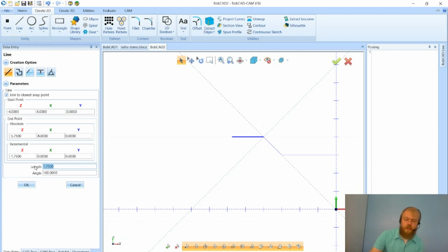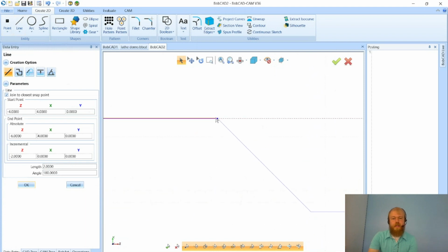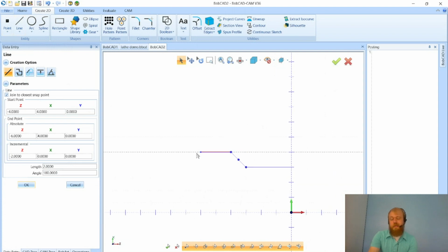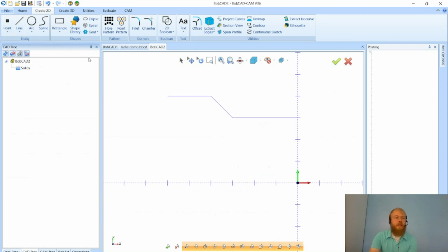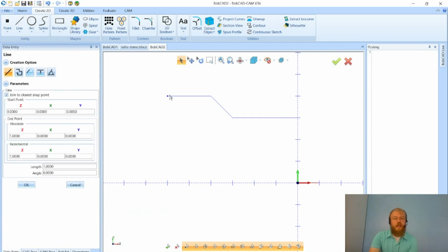Let's go over 2 inches. And maybe we'll just focus on that. We'll make these a couple of arcs here, and then I can make the solid model here by first closing things off. So if we're looking at the turned part here, I'll go to line. From the endpoint here, we'll go down to our z-axis, z0 there, and click there. And from this area here, I'll click and go down to z0 and click OK.